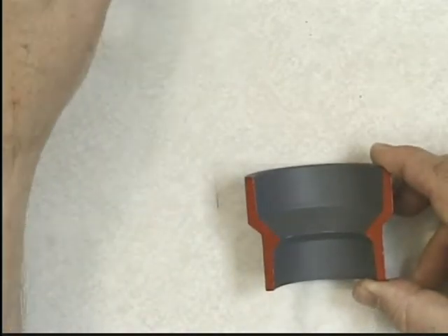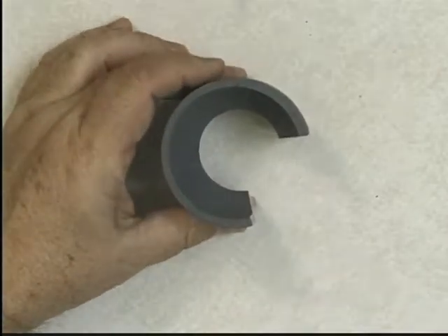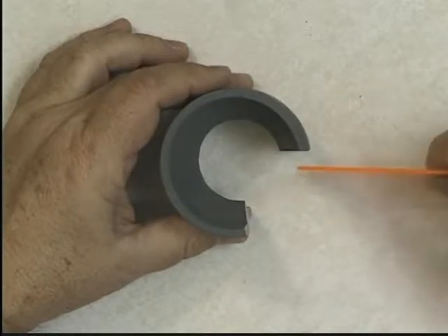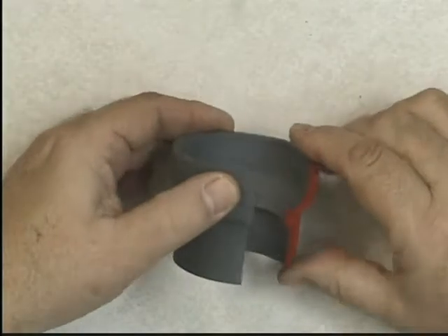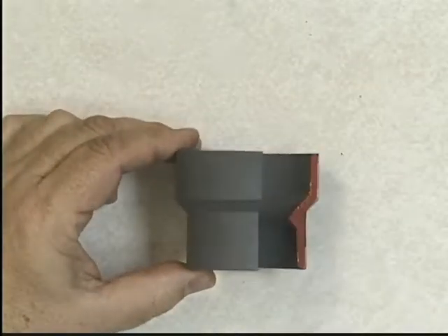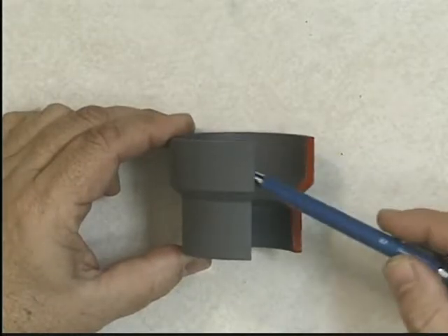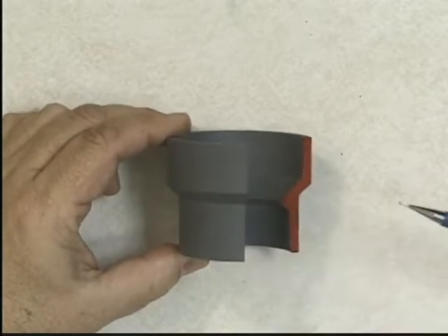In the case of the half section view, remember, we cut part way through and then out. And if I had a front half section view, you could see that half of that view would be cut, and in the other half we could see the outside. And on symmetrical objects like this, half section views are very common because you can see both the exterior and the interior in the same view.